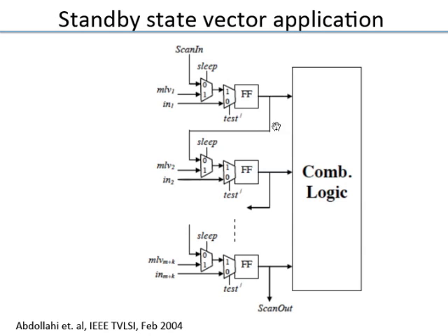Once you figure out through analysis, when you do the design you know what the logic is, and each gate has certain bit patterns which give you the best, you put all of this together and come up with the bit pattern which will give you the best reduction in standby power. That bit pattern you need to apply. How do you apply it? You apply it here. So you have to modify your circuit now. You have to put a mux here. So these muxes are there.